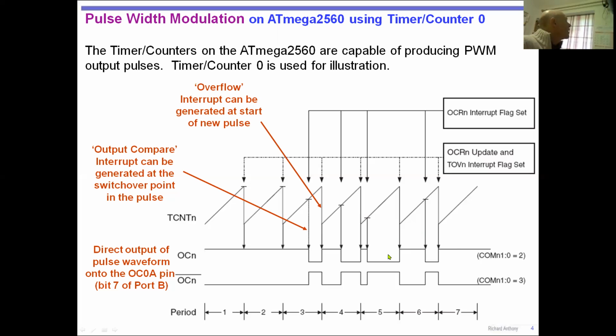And if we then set a midway marker, that's the other part of the cycle. The midway marker is basically when the count value matches what we call the output compare value, which we already talked about when we talked about timers. This is how you set the time interval. You set a value which is called the output compare value, where you want to count to. Basically the counter starts at 0 and counts up, and when it gets to the value you've chosen, that caused, in the previous examples, an interrupt.